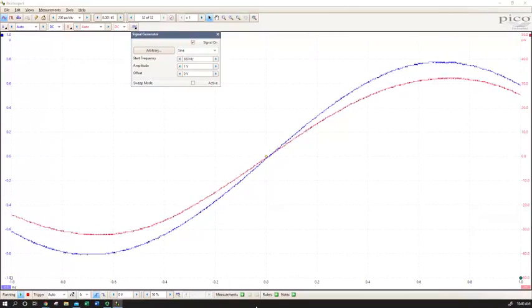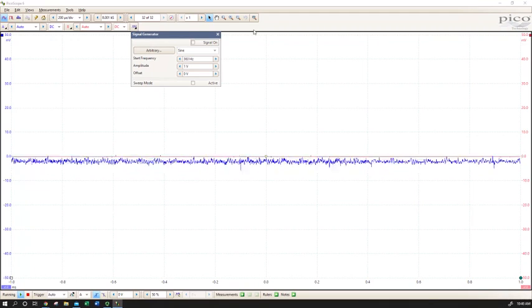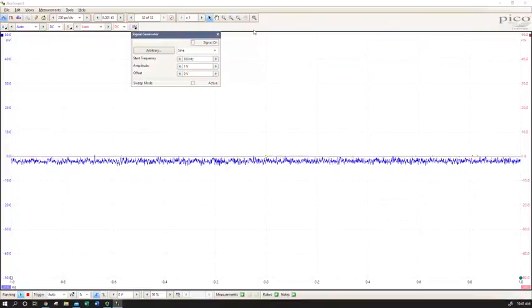That's huge. That's over an order of magnitude larger than my largest standalone inductor that I had in my kit. So by going through this exercise, I effectively gave myself a large number of larger inductors. Now, in addition to my 100 millihenry inductor or 0.1 Henry inductor that I had, I now have a nominal 0.2, a 0.6, and a 4. So I can now build circuits that would require much higher levels of inductance.